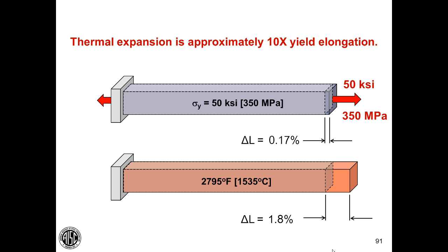Now, why does that matter? Because the weld metal goes in hot and expanded. And of necessity, it volumetrically contracts. And to accommodate that contraction, something must yield. The steel yields and yields, the weld yields and yields, until finally the contraction strains in the weld metal are exactly resisted by the surrounding steel and the strength that it provides. That's why we have residual stresses in welded connections. And that's why we have to accommodate this ductility in the design of connections.